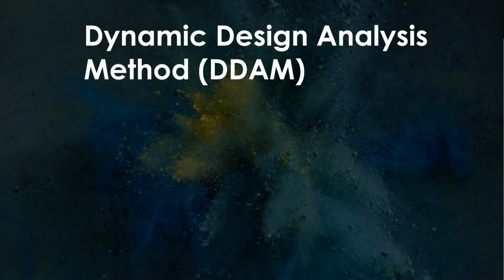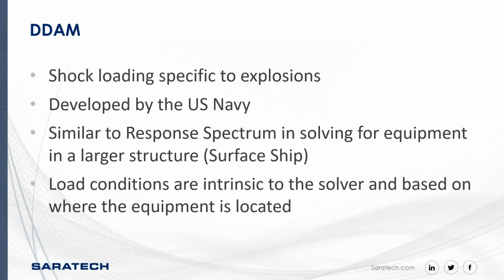And then next we've got our dynamic design analysis method, also called the DDAM analysis. DDAM is specific to shock loading for explosions. It's developed by the U.S. Navy and is required, as far as I understand, for all their naval applications. It's very similar to the response spectrum in that you're solving for equipment in a larger structure, but in this case, the structure is a surface ship.